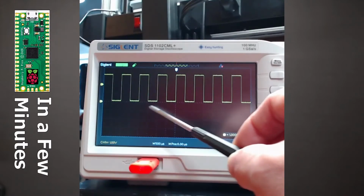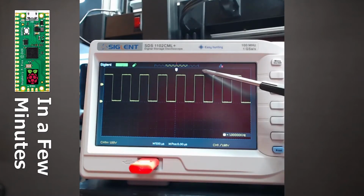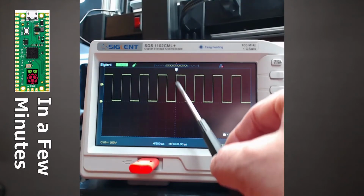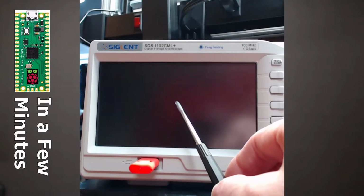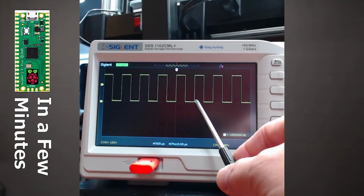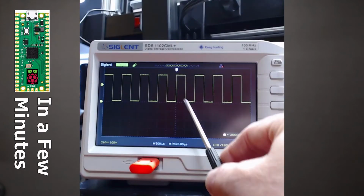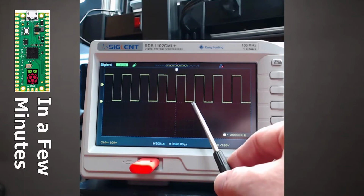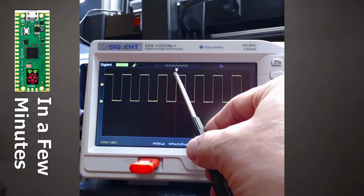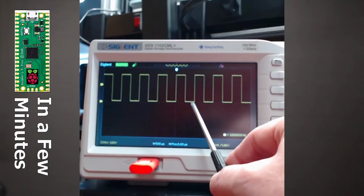Now what we're looking at is time from left to right, voltage bottom to top. So 0 volts, 3.3 volts, and then this is time going to the right. And what we're seeing, this would be one cycle from here to here would be one cycle. And you'll see that half the time it's on and the other half is off. And we refer to that as 50% duty cycle. 100% duty cycle would mean that it's always on, and a 0% duty cycle would mean that the signal is always off.